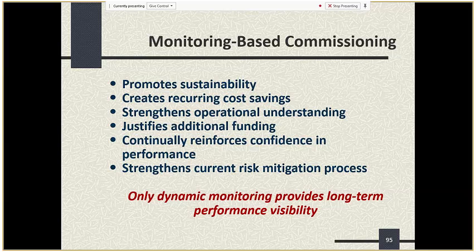Correct. Summertime, we're going to be more efficient, since our base load is higher in the evening. Yes, and so the one component is everybody tends to think about dry bulb temperature, where it is really the humidity levels. That was my point about the range. It's that latent load that's really probably a bigger variable. Correct.